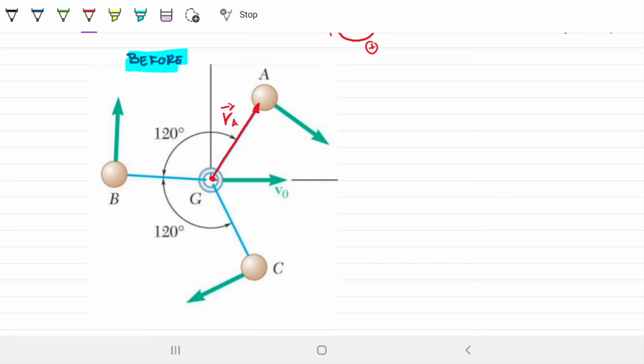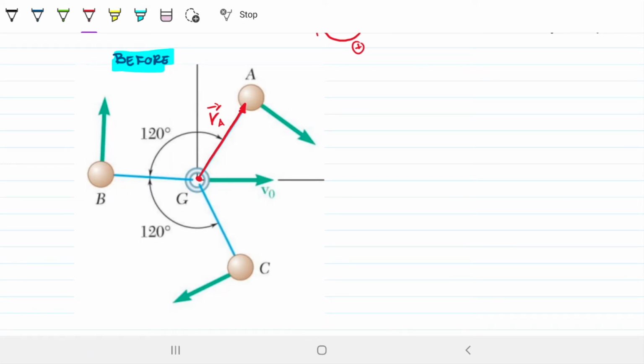Because what's happening is that this vector here, vector velocity, is changing as my position of ball A is changing, right? So when my ball A is here, for instance, my velocity vector is dead downwards, and then my vector RA is going to be like so. And what happens is that the angle is always 90 degrees between them. So this is way simpler for us to calculate, because the angular momentum for A is simply the mass of A times RA, which we happen to know is 200 mils, times the relative velocity that was given from the start.